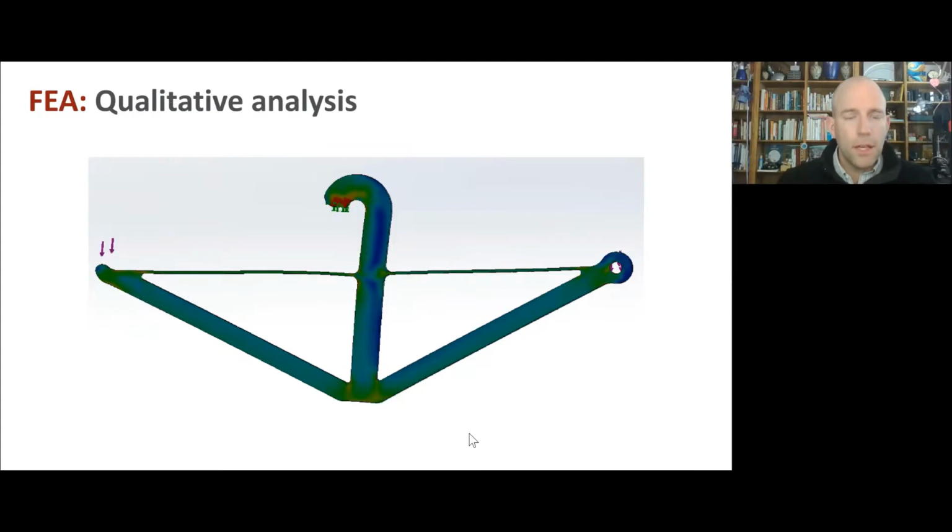And I actually used the evaluate measure tool in SolidWorks to measure the precise distances between these things where I was going to apply my load. And a little tiny imbalance in that force can actually have a really big impact on the deformation of the structure and its peak stresses. So something to be careful about. But the deformed shape looks okay.